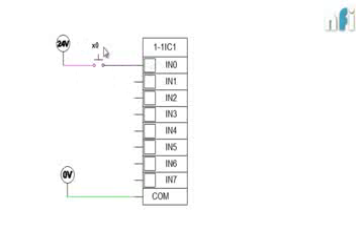You may find such kinds of switches in your panels, in some other machines. You may find some green buttons. So this button is connected in this way. It is connected to some inputs and then common is giving some 0 volt. So similarly, let's connect some other switches.